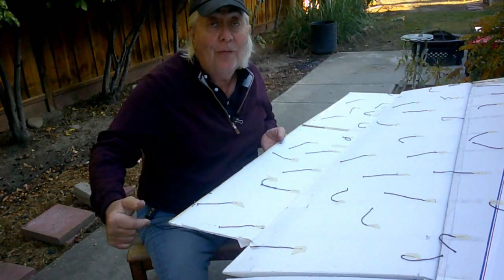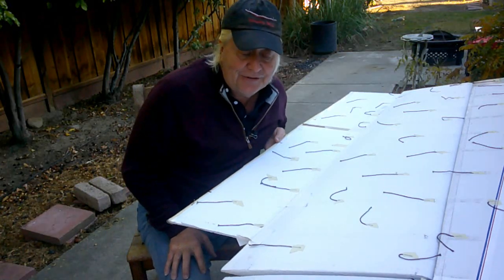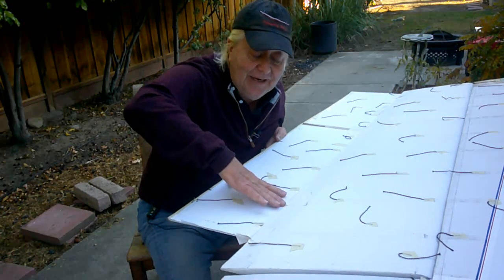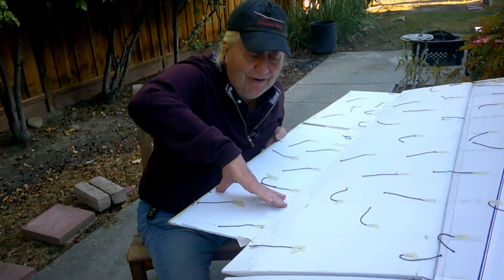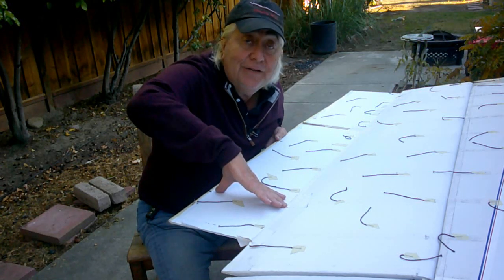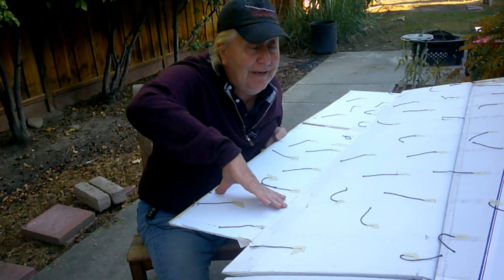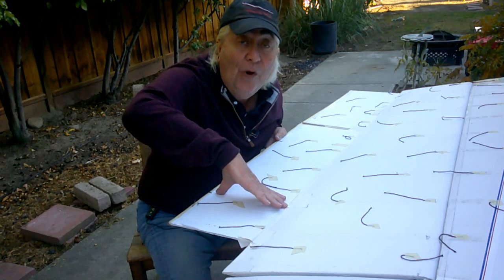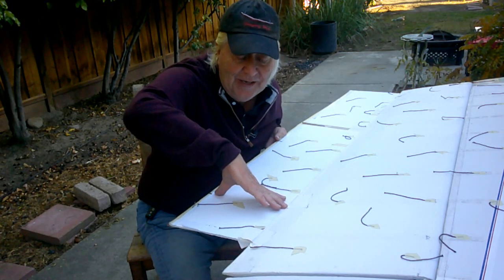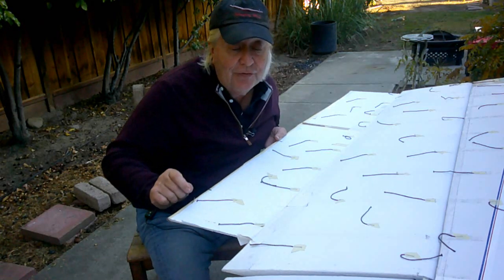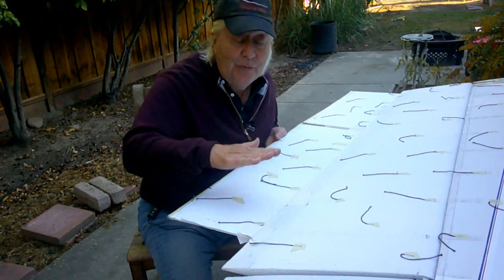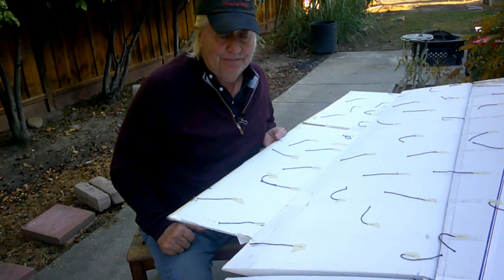Then the chord was 33 inches. This is a 9-inch extension. Wow. I needed 32, had 33. Is that right? 24 plus 9, yeah, 33 inches. So I'm 1 inch more than the minimum I need. So I'm a skosh over 500,000 on the Reynolds number with this tacked on the trailing edge.